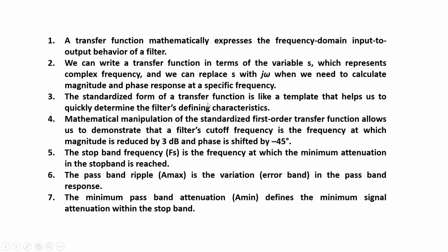The standardized form of a transfer function is like a template that helps us quickly determine the filter's defining characteristics. Mathematical manipulation of the standardized first order transfer function allows us to demonstrate that a filter's cutoff frequency is the minus 3 dB point, where the phase is shifted by minus 45 degrees.